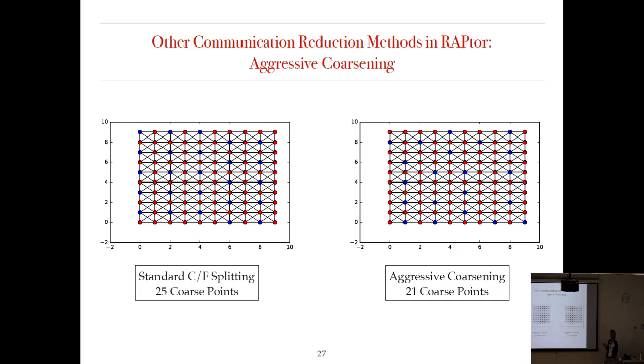This becomes very obvious when you have a very large problem, and so your savings will not be 4 coarse points. It'll coarsen much, much more quickly. It actually is almost required for most 3D problems, if you're using classical AMG, to use aggressive coarsening. Otherwise, you tend to run out of memory. And then it also goes significantly faster.